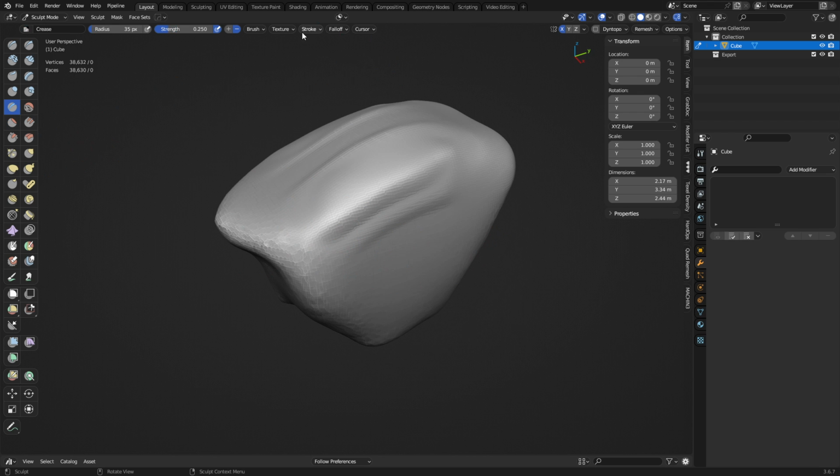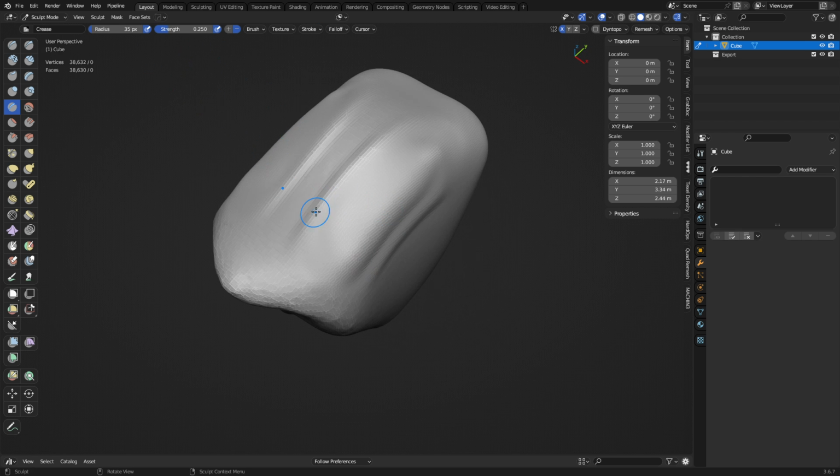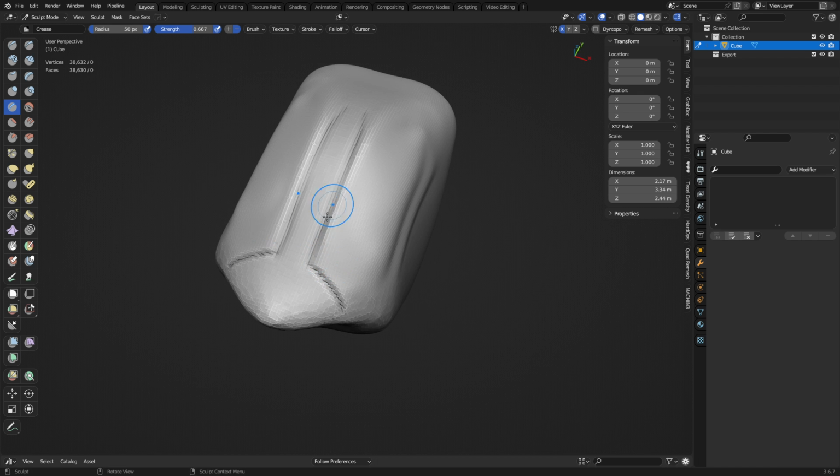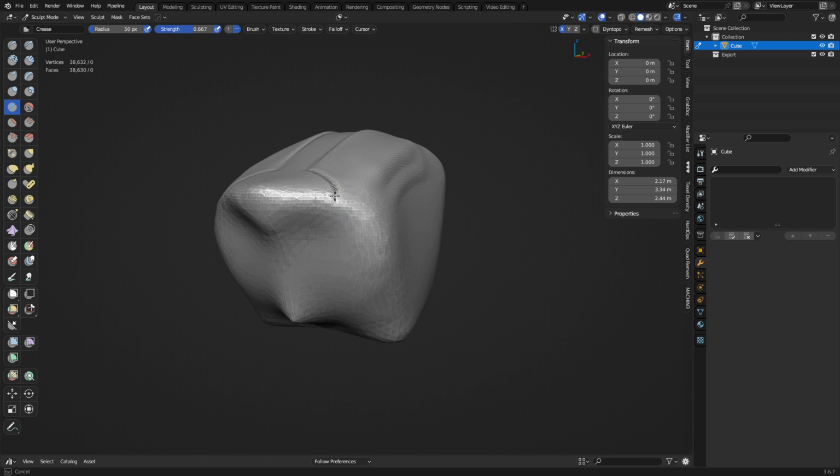Now, the crease tool. Set the falloff sharper, and radius on for your pen pressure sensitivity if you're using a pen. I'm using a tablet, just a cheap one. And you can see here, it's very soft, right? If we use very little strength pressure when sketching here, we can pin things in very easily. This is a way a traditional sculptor might go about doing things with something like a pencil, and this is very effective if we wanted to start working with it in this manner.